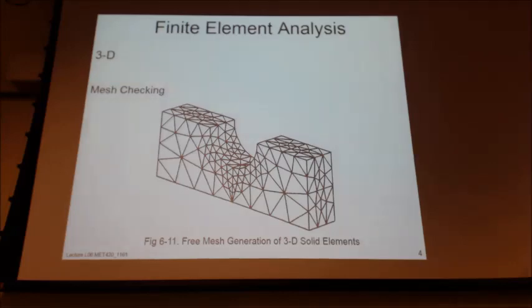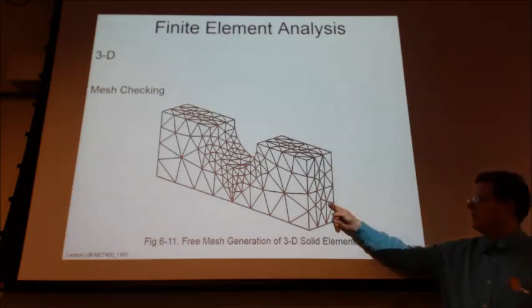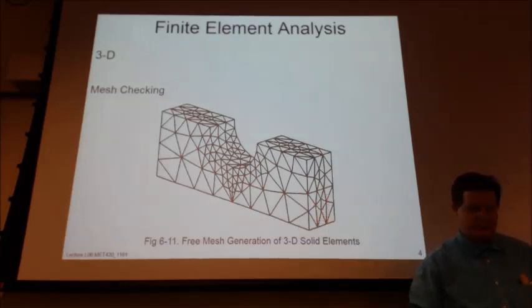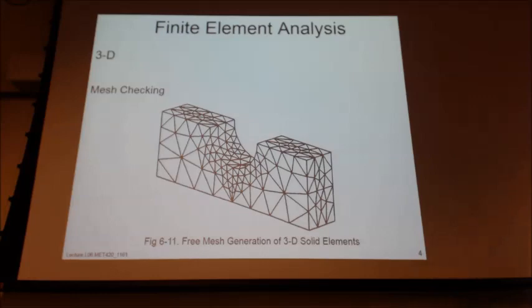One of the things it's checking for, when you have all these different size shapes, is that you have no distortion issues, and it's also going to look for free edges, so some micro voids, because we can't tell what's going on inside. All we see is the surface mesh, so it's checking the inside for voids. So on a larger, more complicated model, it's a good idea to do that before you tell it to analyze.